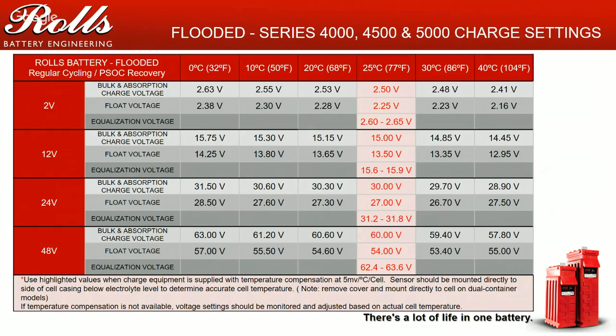Again, these voltage settings, the ones in red, are assuming that you're using temperature compensation. If you're not using battery temperature compensation, then that's a serious problem, because you should always be using temperature compensation. Without it, you're not properly charging your batteries.